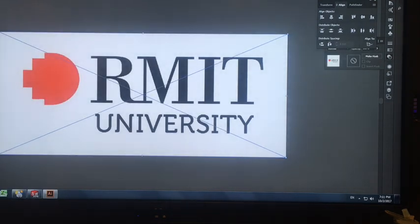So you've got to have it selected. We can go up here, Image Trace, and there's different options. So it might be black and white logo that you try, or line art, or a tech drawing, or 3 colors. So we'll try black and white logo. All right, so it's traced it. To actually get the vector line work, you then press Expand.